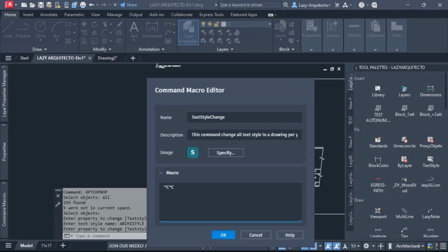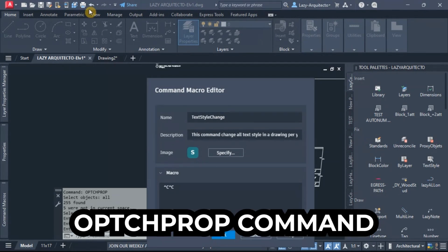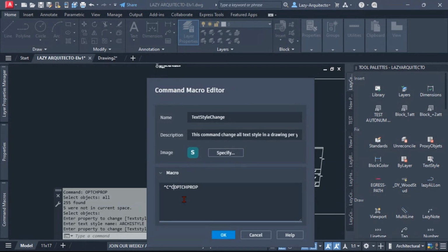Next, do you remember what we did on the command line? Well, what we did, I'm seeing here on my second screen, is we used the obj prop command. If you remember some of those special characters again, we need to let AutoCAD know two things. One was that we want to use the standard form or definition of a command, right? Because commands can be modified by AutoLISP or other custom programs, and we don't want that. We want to use the standard version. We let AutoCAD know that by using this period or dot, so that's what we're going to use before our command.